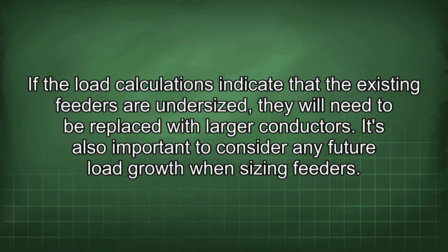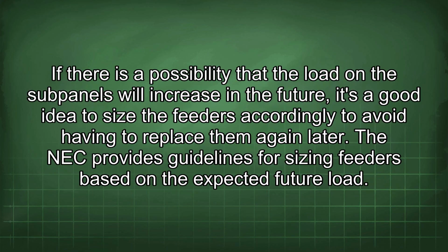with larger conductors. It's also important to consider any future load growth when sizing feeders. If there is a possibility that the load on the subpanels will increase in the future, it's a good idea to size the feeders accordingly to avoid having to replace them again later. The NEC provides guidelines for sizing feeders based on the expected future load.